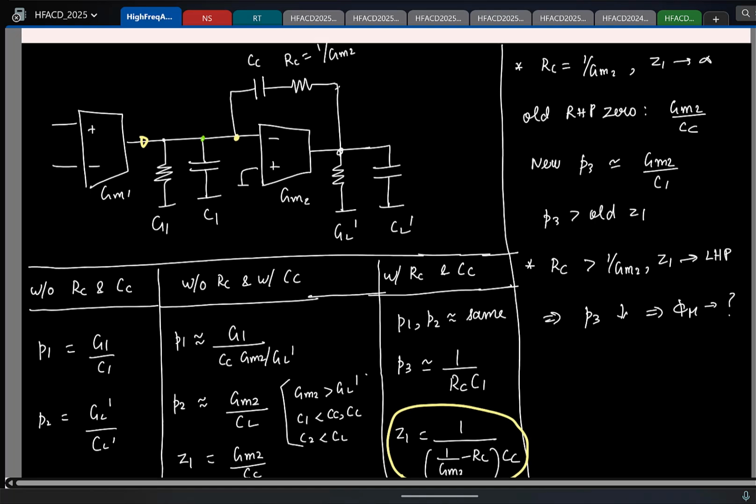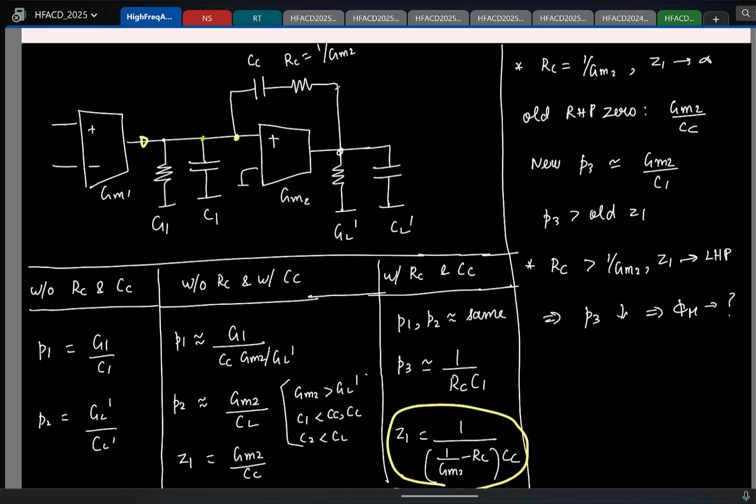Yes. Why did you connect the output of GM1 to the negative terminal of the second? So you're saying why can't I have this one, right? Any answers for that? Yeah. Remember that this GM is going to be a single stage GM. That is, it takes a single input, single output. Simplest realization is common source. Common source, the gain is positive or negative. So that is fine, but then, if we don't use the common source, then we will not get a positive or 0.